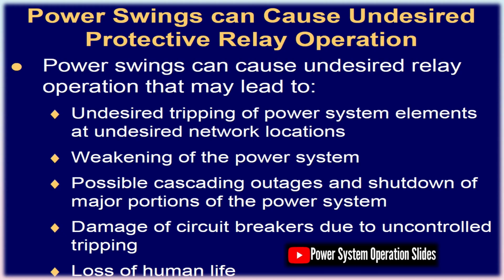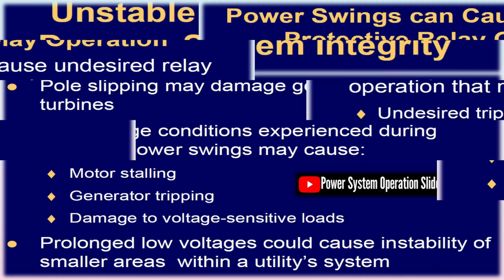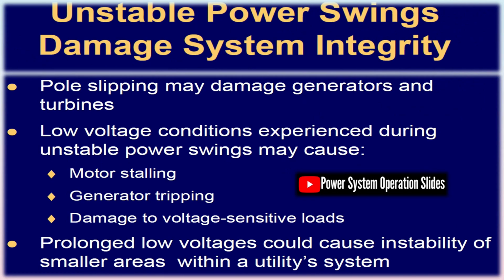When a fault occurs on the transmission line, the effective reactance increases due to an additional shunt reactance XF introduced at the fault point. Different types of faults, such as single line to ground, line to line, or three-phase faults, affect this equivalent reactance differently. For instance, single line to ground faults have a smaller impact on the system's reactance, while three-phase faults can completely block power flow between generators.